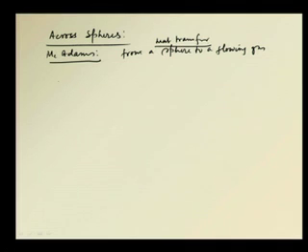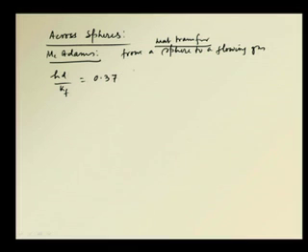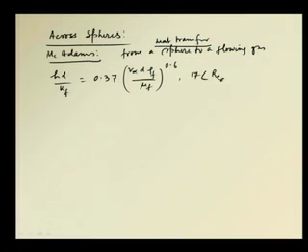Okay. So according to McAdams, h d by k_f, where f indicates that it is evaluated at film temperature, is equal to 0.37 times (V infinity d rho_f by mu_f) whole to the power 0.6, where 17 less than Re_D, and D is the diameter of the sphere under consideration, is less than 70,000.